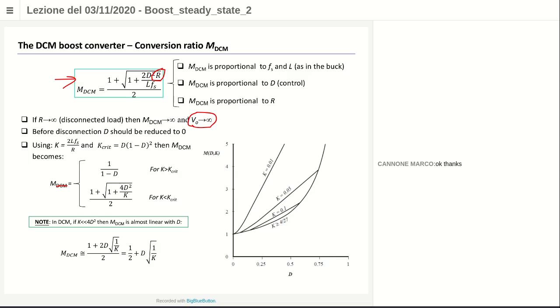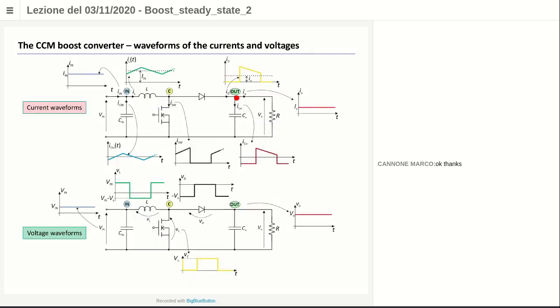Typically, the boost explodes. This means that the output capacitor explodes. The electrolytic capacitor, as I said before, has a maximum working voltage that is tailored to the voltage you can have at the output, plus some safe margin.